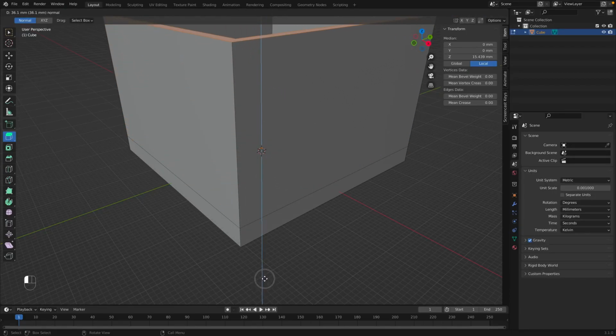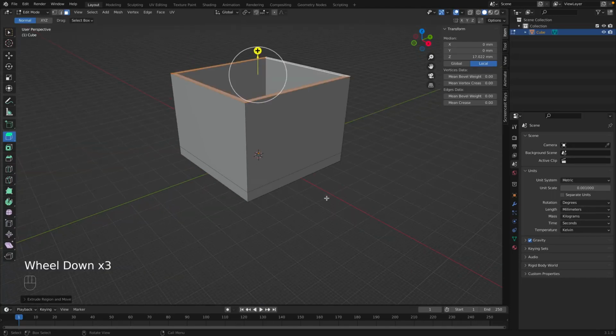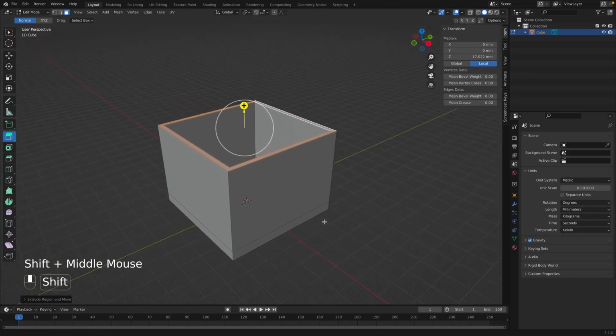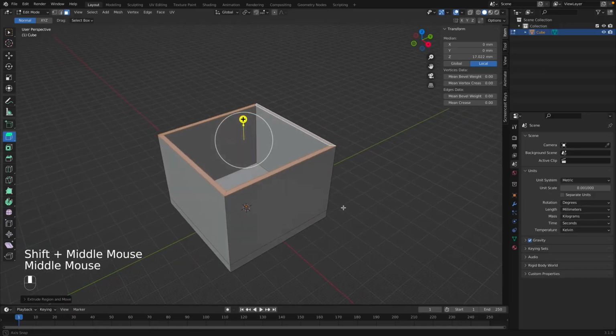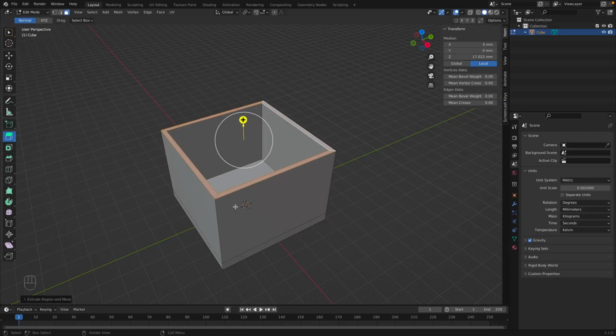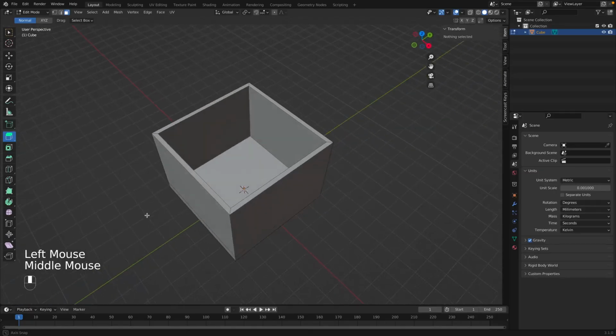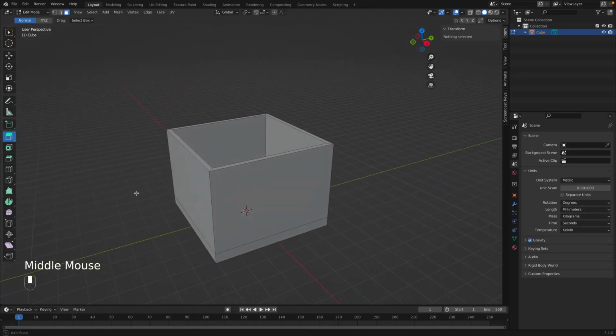And let's go about, you can see the dimensions on the top left. Let's go to about 40 millimeters right there. Now if I zoom out, hold Shift to pan while using the middle mouse button. And you can see, do you like that? And we say, yep, that looks good. And then go ahead and click outside of it to confirm. And now we have our box.